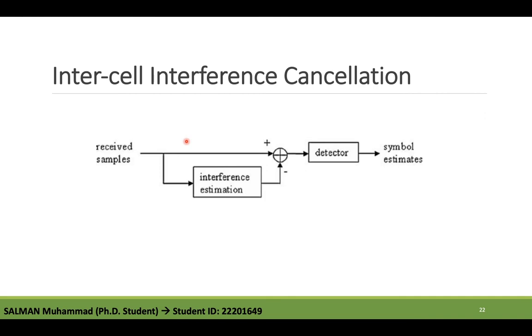The first approach is called the hard inter-cell interference cancellation, which is based on the use of hard decisions of the demodulation. This approach is one of the simplest ways of realizing interference cancellation. However, it is not efficiently applicable to OFDMA since the only source of processing gain in this case is the channel coding present in the system, which is not exploited.